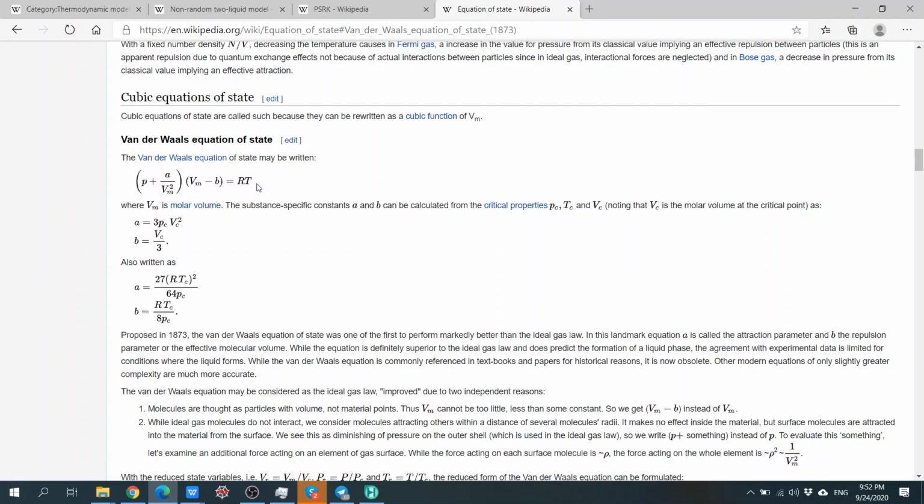So if I need to pump or compress or let a fluid flow at a certain temperature and at a certain pressure, what is the size of the pipe, for example? I need to know the volume of that fluid. So you can use these equations to calculate the volume, and then you know how big the pipe or how big the vessel is.